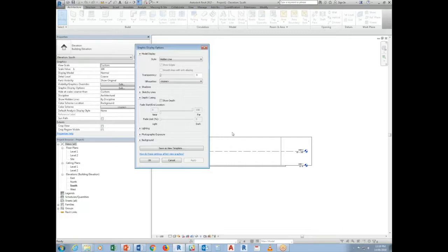So you have to select that item to do this? Yeah, basically when you go to show, it says whatever's near is 100%, and if it's far, it fades. So let's say this one, I'm going to just make it dark. If we had 2 walls, and then we changed that view depth, would that change the view depth for both of them, or do we have to select which one we're applying it to? If you are using it as a view template, it means all the views using the template are going to have the same thing. I think elevations and sections work this way as well. I could never get the settings to look correct.